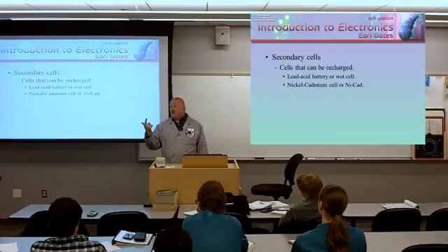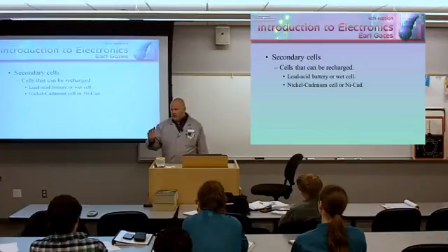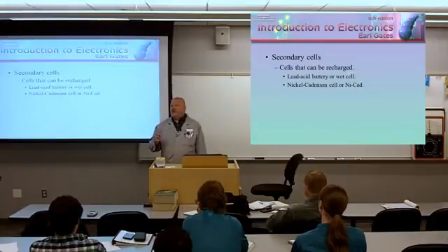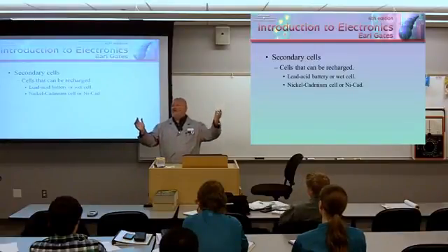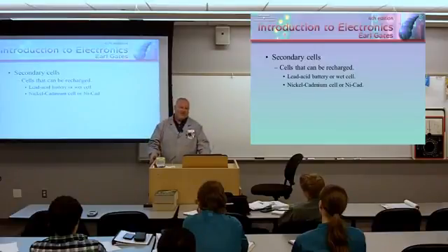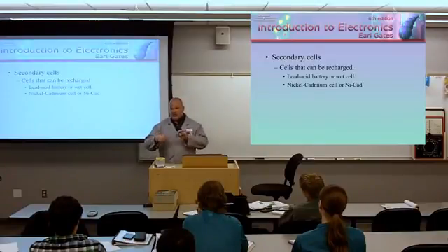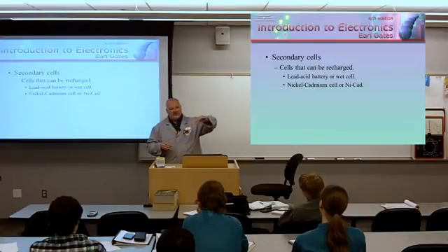Like I've got a cordless drill at home, a Makita. I got a quick charger for it. Worst thing you could do. Mine still works. But you know how those quick chargers work? They actually have a temperature sensor in the battery pack. When the battery starts to get hot, it must be full, so it cuts the battery off. That's not a full charge. The only true method of charging a NiCad properly is a timed charge. A trickle charge where you're trickling in a known amount of current and then you bring it gradually up to that 100%.